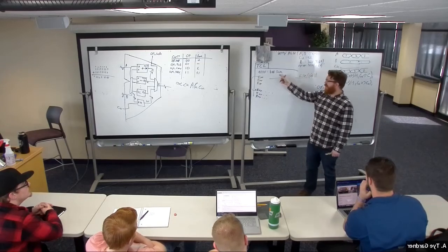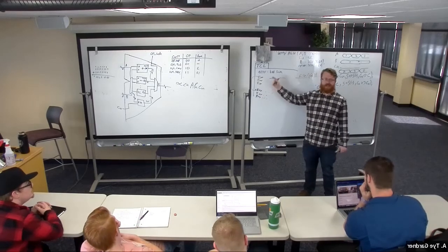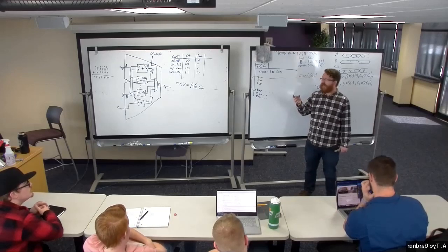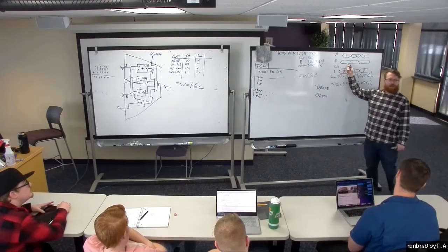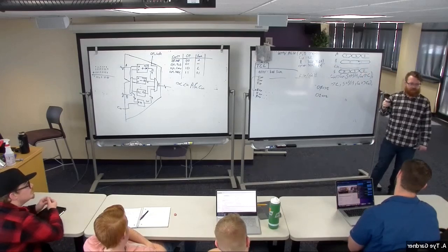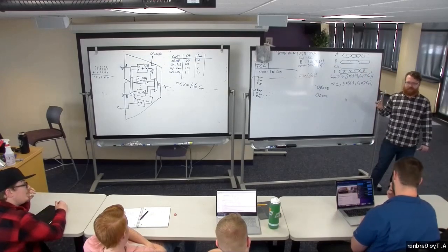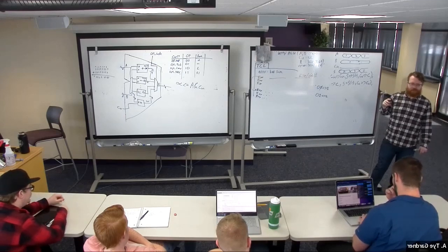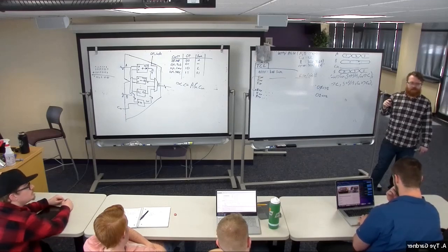If you don't see any error bad sums and no other errors, it probably works. You're probably good to go. You'll want to go check a couple of the waveforms and make sure that it's adding in the way that you think it's doing, because that's all this is doing, it's adding. Once that's done, then you're good to go. Make sense?